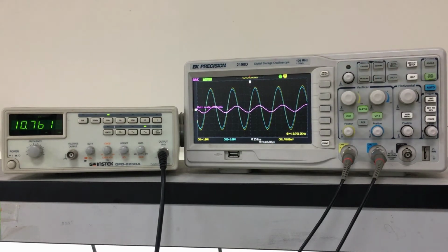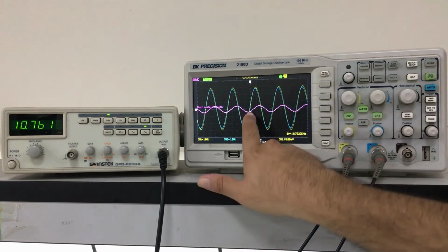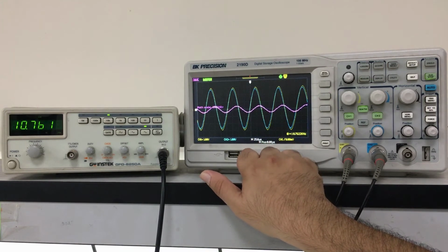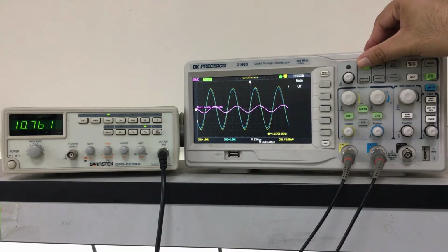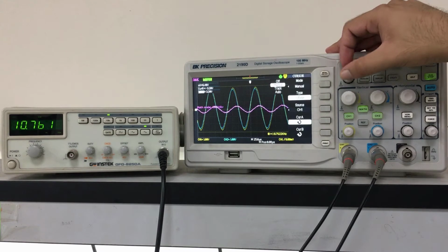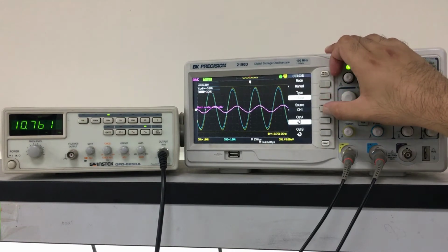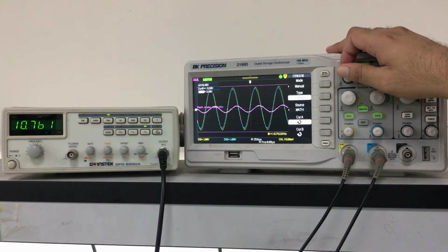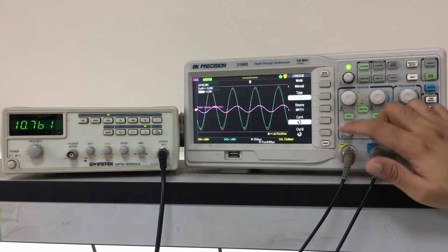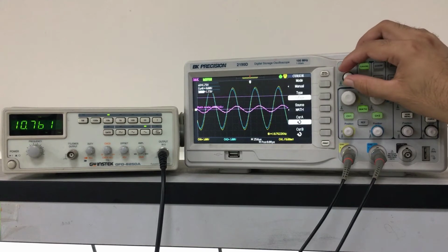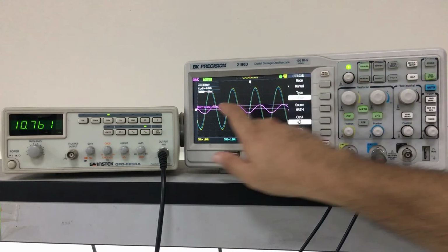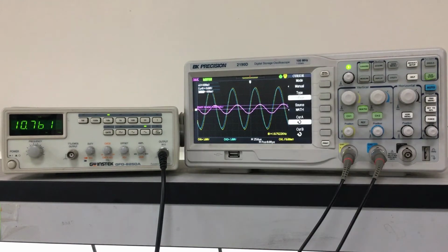We'll need to measure the peak voltage of this curve and also the phase of this curve. So first of all, to measure the peak voltage of this curve, we will need the cursor. We turn it on by pressing manual. The type is voltage. Source should be math. And to measure the peak voltage, we take cursor B to 0 volt and we move cursor A to the peak of the curve. So we get 480 millivolts. We should record that in the table.